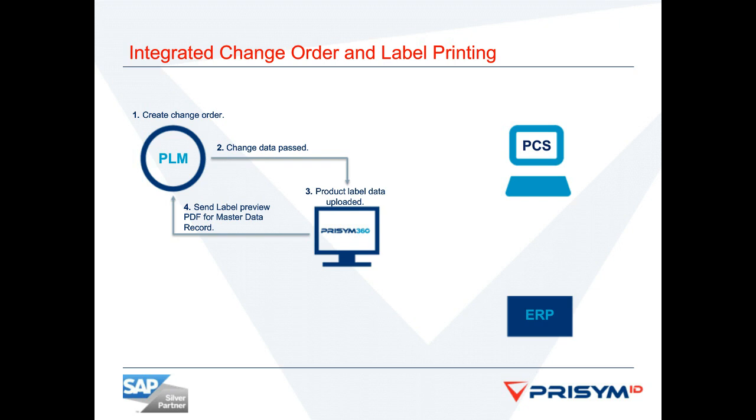This is ready for printing. What it means is that the template, which earlier was in a non-production status, is now ready for printing, because unless the PLM system sends a command saying this is ready for printing, you would not be able to use that template for printing on the shop floor. That's the kind of control we developed. Now, that's basically the designing piece.